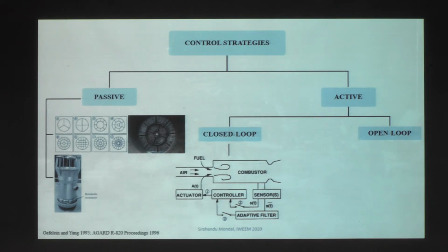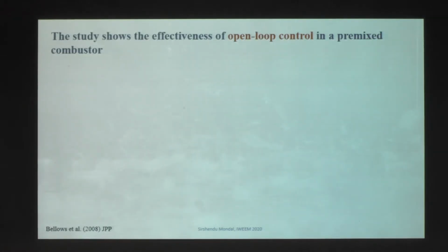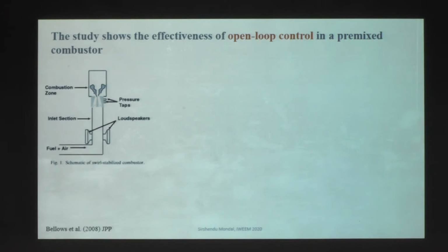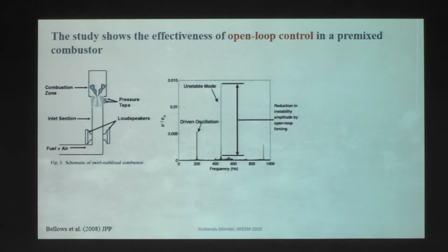So they have also tested in different studies. Just to give you an example, this is also tested in a premixed combustor, a swirl stabilized premixed combustor. They have shown that for some selected frequencies which are non-resonant, they found this particular thermoacoustic mode getting suppressed, where this is the driven oscillation or the external frequency which is still there. So in the amplitude spectrum you can see the mode of thermoacoustic oscillation is completely suppressed,